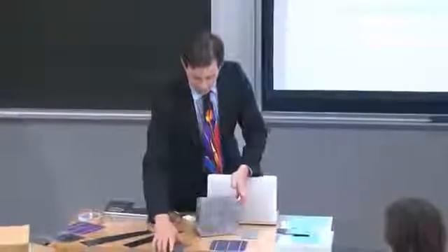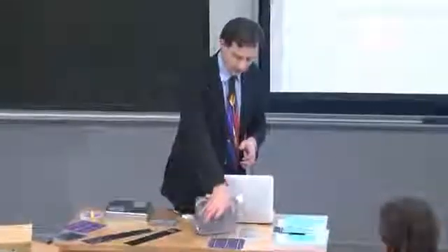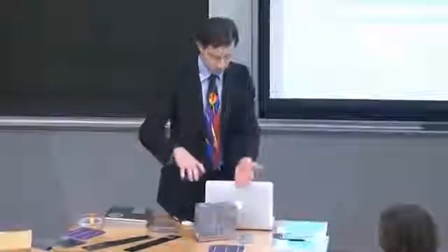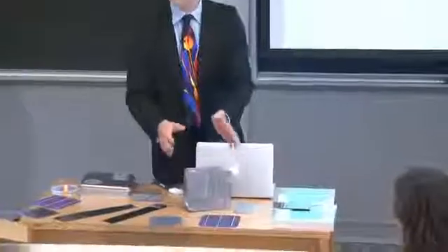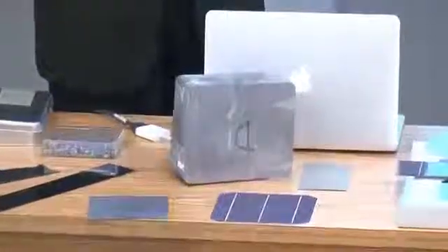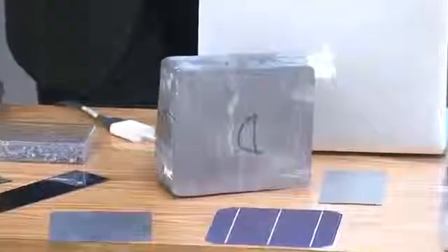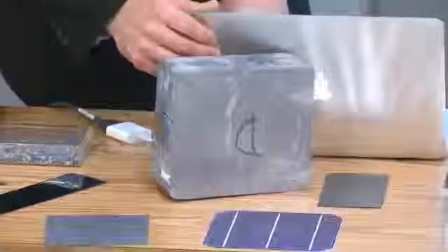And we have to avoid using these ingots, like this one right here, from which these wafers are sawn, right? So your wafers are sawn out of the ingot like this, like shown. During the process, about 50% of the silicon is lost to sawdust. And they said, well, let's develop a better way. Let's extrude the wafers directly out of liquid molten silicon and make ribbons of silicon instead. That way we don't have the sawdust and we don't have to have this expensive ingot solidification step.